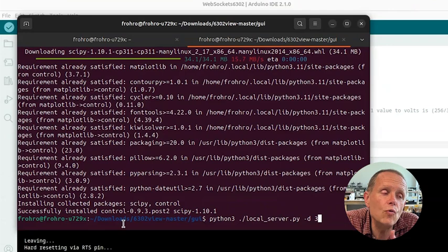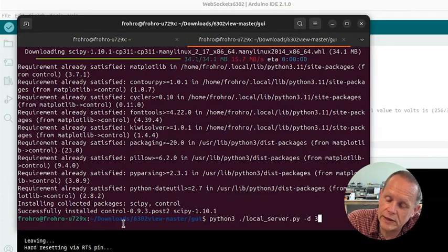And then if you wanted some help, you could use --help or -w, and -w uses a wizard that asks you questions and you answer them. But I got tired of that, so I just use -d3. What does that mean? The -d3 tells it I'm using an ESP32 processor, so I don't have to answer all the questions.